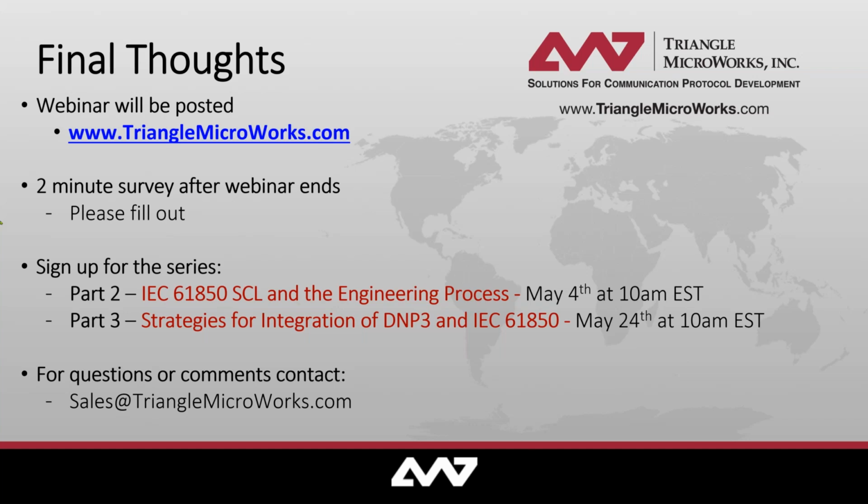Well, it depends a little bit on the areas. In some countries, they are using almost only 61850. In Europe, in many places, we anyway didn't use DNP3. There was the corresponding thing, 60870-5-101, 104. That was very popular. But in many countries, the utilities are now completely applying 61850. In North America, DNP is still much more used, but 61850 usage is growing, and mainly in the context of digital substations, where they include sampled values and these communications.